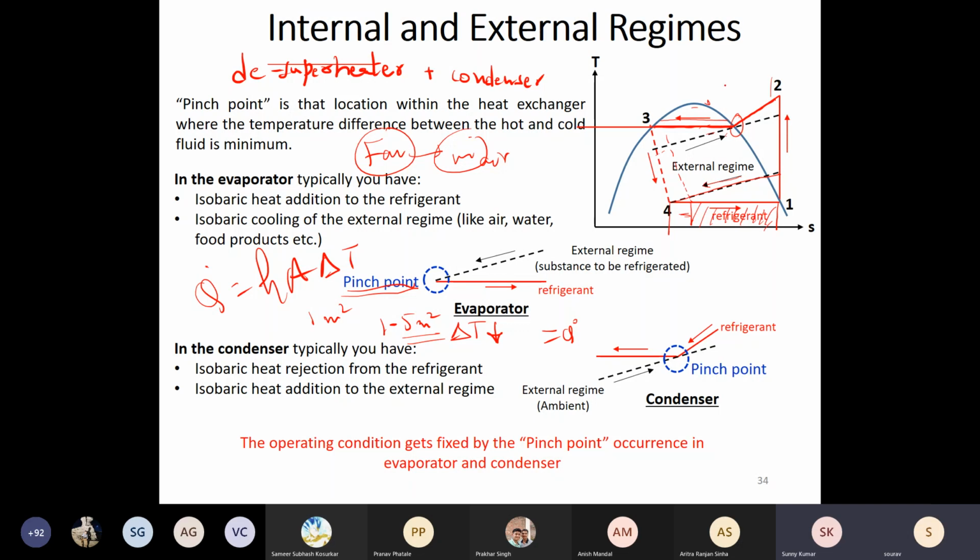The cheaper AC will use smaller heat transfer areas in the indoor and the outdoor unit. What is the repercussion? Compressors are the same for both. The repercussion is that even if the compressors are the same, they will not be seeing the same pressure ratio. One, because it has a smaller heat transfer area, will be operating at a higher condensing pressure, because it will require larger delta T to have the same amount of heat transfer. So one would be probably operating here. The other, which has a larger heat transfer area, would be operating at a lower pressure. Same goes over here also.